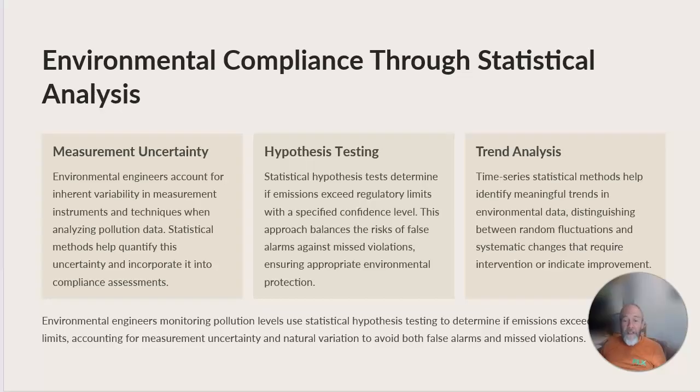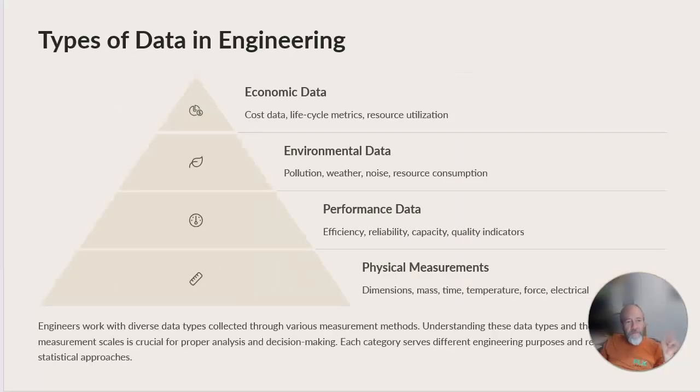Based on what's going on in the real world, whether it's raining or not raining, and based on how that data varies over time, taking values of that pollutant at multiple places upstream allowed me to make predictions at different times of what the values would be downstream and whether violations would occur. Environmental compliance. And it was a complete statistical analysis.